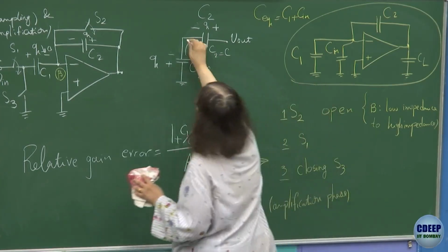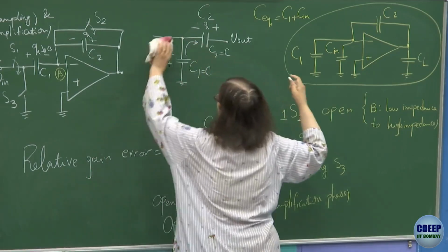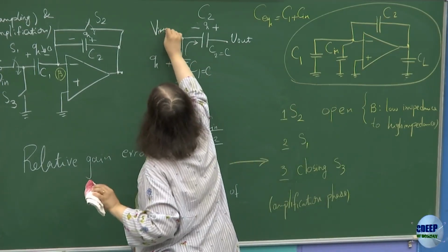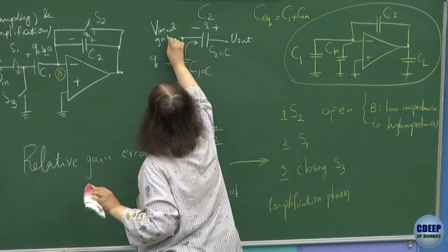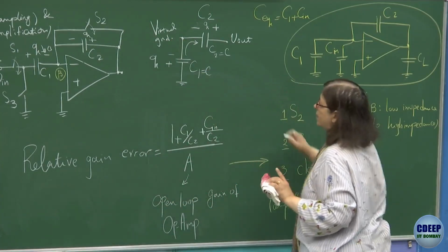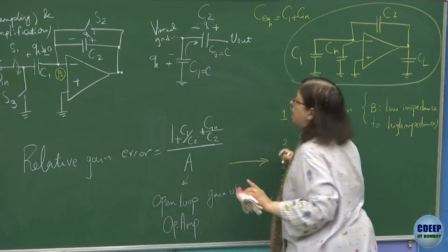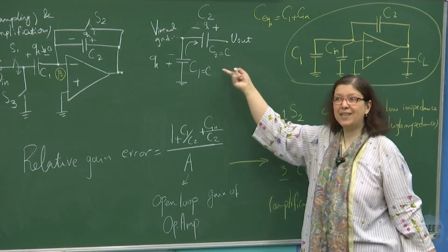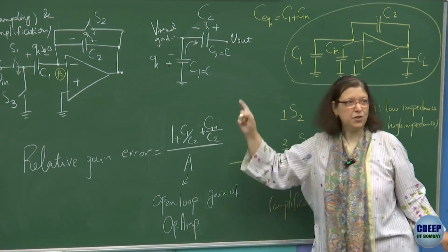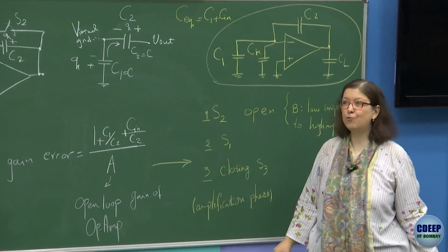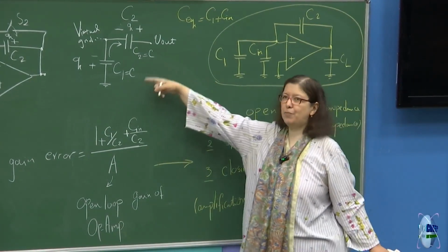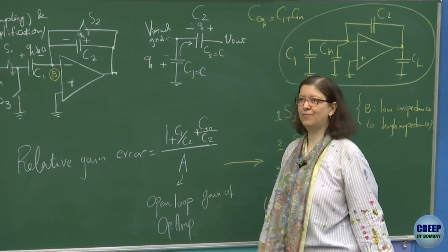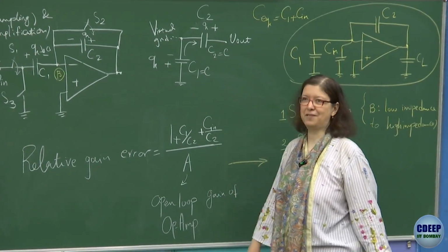Suppose I just put a switch this way. So eventually it's a virtual ground. Suppose this is virtual ground. So if it is virtual ground, then I show connections. Charge on this capacitor will be discharged into C2, but it will add to the charge in C2, right? So charge on the capacitor C2 now becomes 2Q. That means by just choosing the polarity, you can get double the charge. That means with the same capacitors, you get gain of 2. That's the advantage of the switch capacitor circuits.